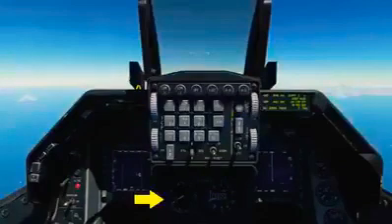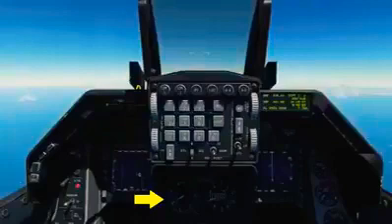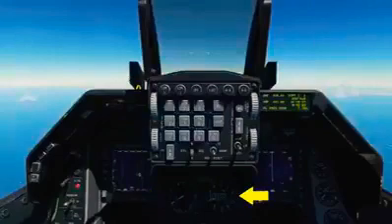The airspeed and Mach indicator is pneumatically powered by the pitot-static system. Airspeed is indicated by the outside gauge and pointer between 80 and 850 knots, and Mach is indicated by the window near the top of the indicator between 0.5 and 2.2 Mach. The right triangle in the indicator indicates the VNE, or velocity never exceed, and the green triangle can be set by the knob. The altimeter is servo pneumatic and can indicate altitudes between -1,000 to +80,000 feet. It has both a primary electrically powered mode and a secondary pneumatic mode. If in secondary mode, the pneumatic flag appears on the gauge to indicate pneumatic mode.